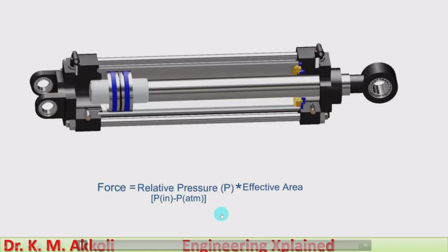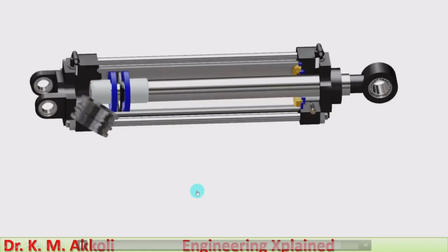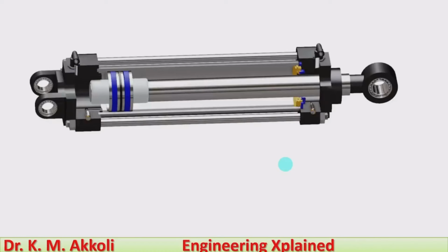During the retraction stroke, on the rod area there is no pressure acting, therefore that is subtracted from the total area. Therefore P multiplied with the partial area gives the retraction force, which will be lesser. Like this, the double acting pneumatic cylinder operates. Here the frictional forces as well as the cylinder bore diameter and the stroke length are all considered during the design of this pneumatic cylinder, which is used for linear motion and linear actuation force.